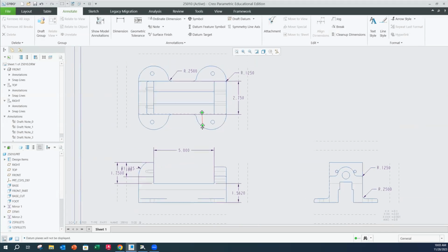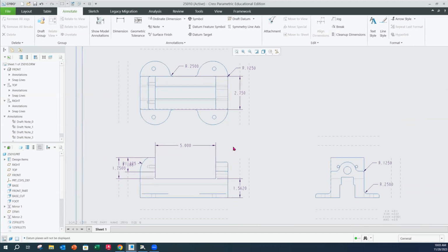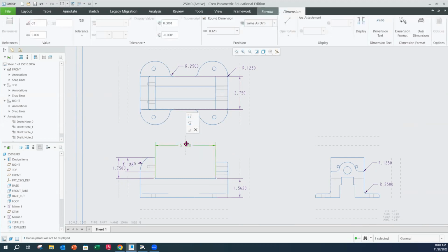All right. Now, again, here I'm going to figure out where I want these to go. So we do have a drawing guide that is out there, but I'm not going to pull that up. So I'm going to grab this dimension here. I'm going to pull it up. Remember, you have to click on it once and then it's activated. And then I'm going to pull this up so that I am not touching the part. I'm maintaining my gaps. Then I'm going to move this one. I'm going to select this one. I'm going to move this out. Okay, this is going to remain in this view, so this is totally fine.